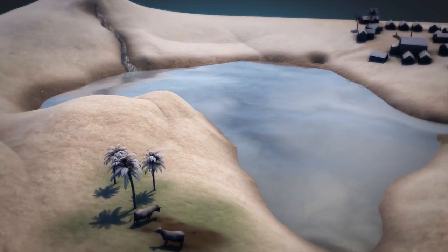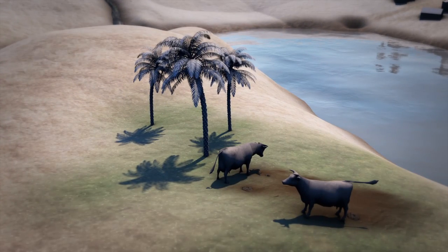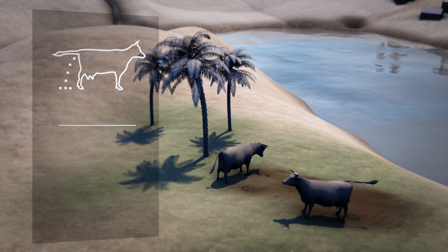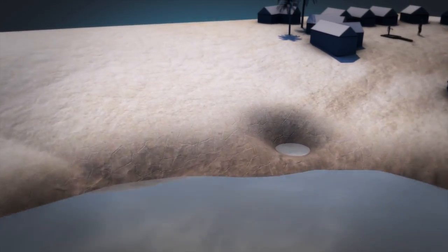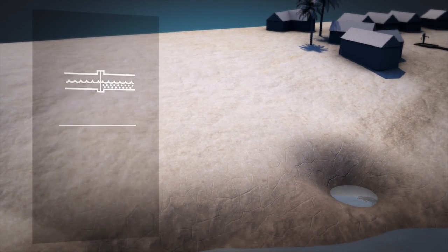First, the water resource itself can be contaminated from contact with human or animal feces. Surface water often contains fecal bacteria, but even groundwater aquifers can be contaminated by inadequately managed sanitation. Even if the water resource is clean, or if water is purified at a treatment plant, it can become contaminated during delivery to the consumer. For example, in a piped water supply, if there is not continuous pressure in the distribution system, contaminated water may enter the pipes through cracks or joints. Another example could be an improperly constructed rising main on a borehole, or suction hand pumps, which are primed with unsafe water.